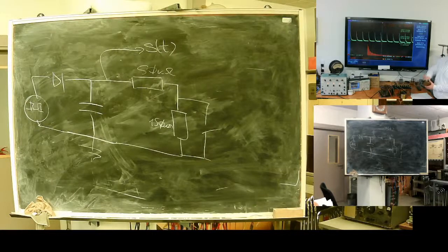See? The process sharpens. And what do we see in frequency? See? It's narrow, then it widens. A sharper change means a wide frequency range. You had some system, everything was fine, and you install a better switch. Better, not worse, which switches faster. Switching faster means a wider frequency range, and the disturbance causes your system to fail.